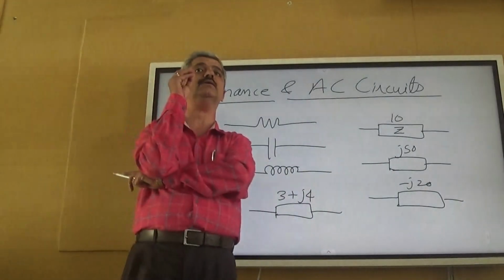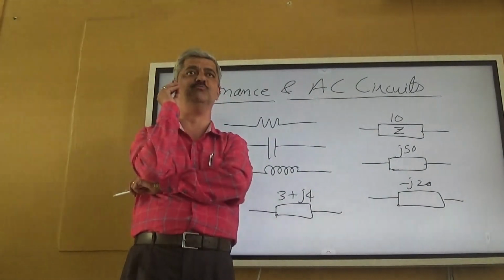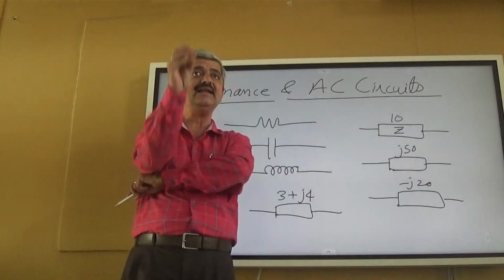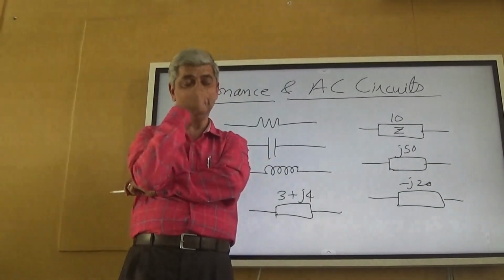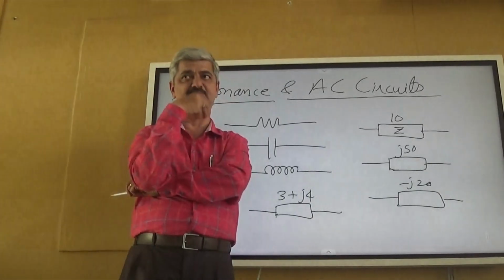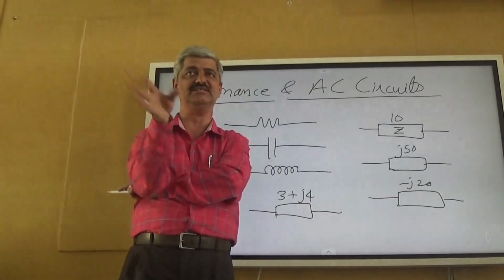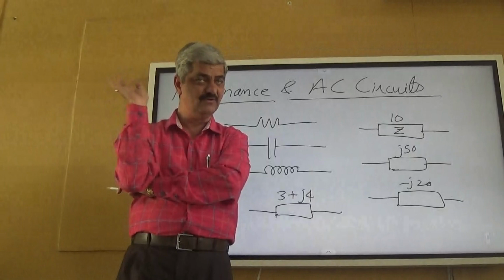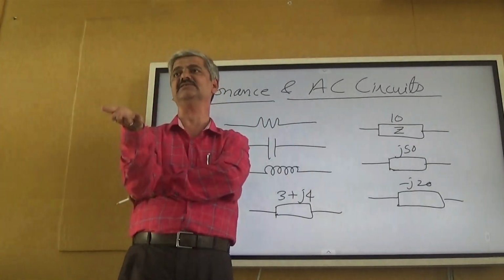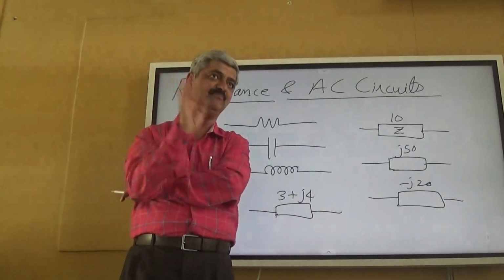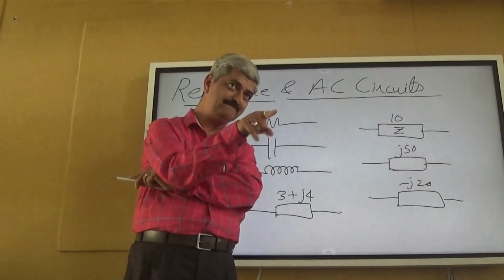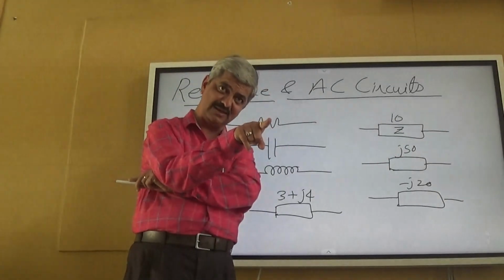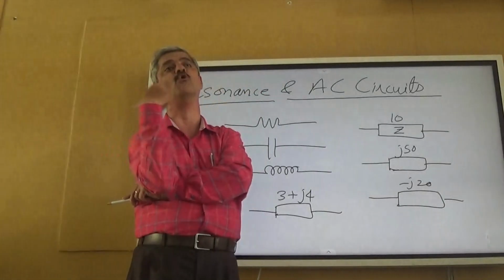For voltage sources sinusoidal at the operating frequency, a resistor exhibits the same resistance throughout the frequency range, whereas an inductor and a capacitor exhibit different impedance at different frequencies. So if an inductor is given, the value L is given, you must know omega.